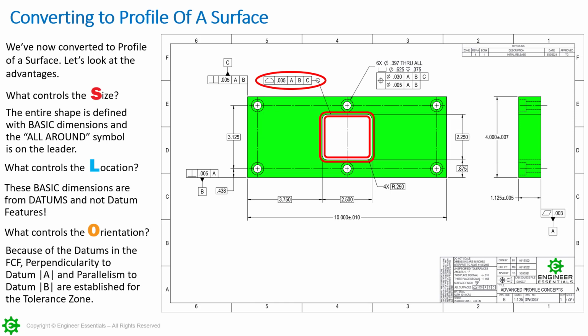Now, like I said, this becomes a very simple measurement because we have datums. So up here in the feature control frame, we have these datum references, and it tells us how to set the part up and how to take the measurements, and also that we are coming from datums now. So this does mean we can simply stand this up on its side on a granite table. Now we would want to use something else like a 90-degree plate to put A up against.